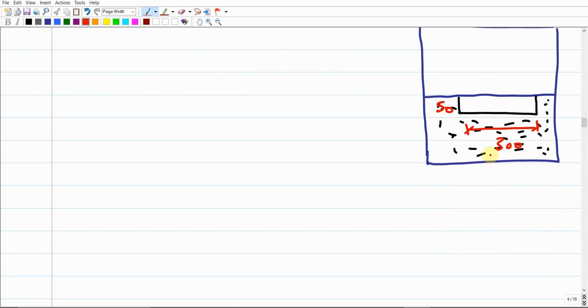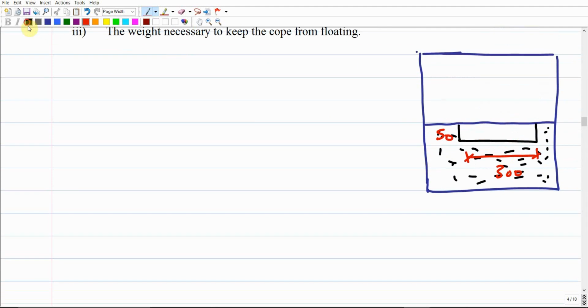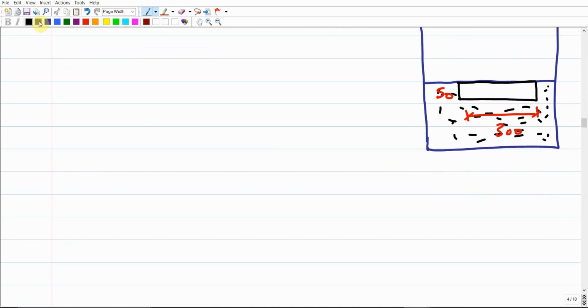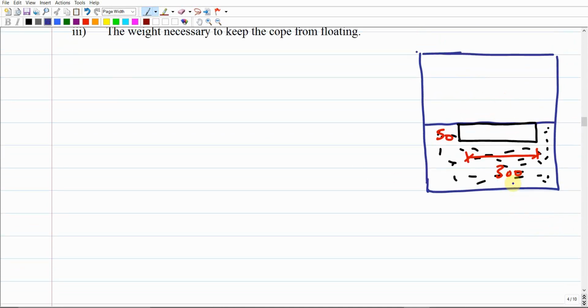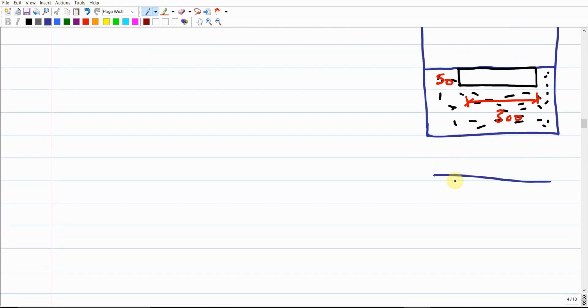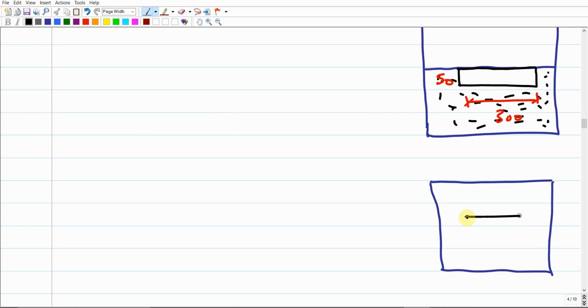If we decided to look at it from the top, do you remember the fifth or the sixth step of the flask dimension in the sand mold design problem? You're going to draw the flask or the mold in this way. If we look at it from the top, it will be seen as rectangular, and the casting will be in the middle like a rectangular shape, right? It's already located here. There is no need to add the A, B, and D dimensions as we did for the sand mold design process.